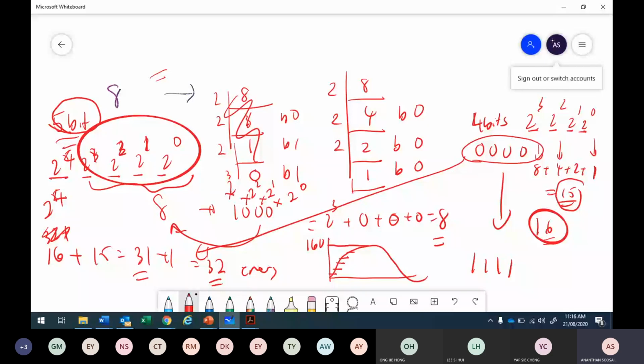Every how many volts can you keep a code? 16 divided by 32, how much? 0.5 volt. Every 0.5 volt you can have a code. Say you take a sample and you got 15.5 volts. 15.5 volts can have a code.